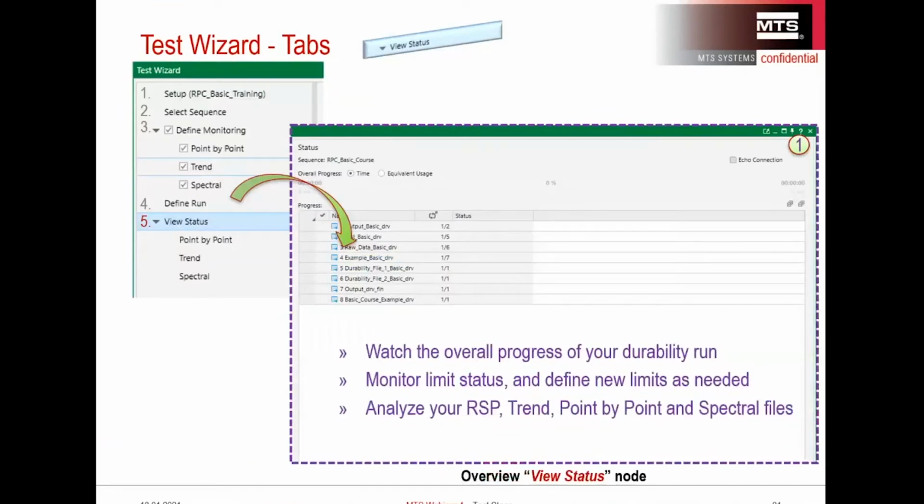Okay, last but not least, we need to have an overview tab to see the progress of our durability run and watch the limits being tripped. The view status node will fulfill this task. So here you can directly make your changes, and there is no need to go back to the define monitoring section to make these changes to continue your run. All related warnings and issues will be shown in this node.